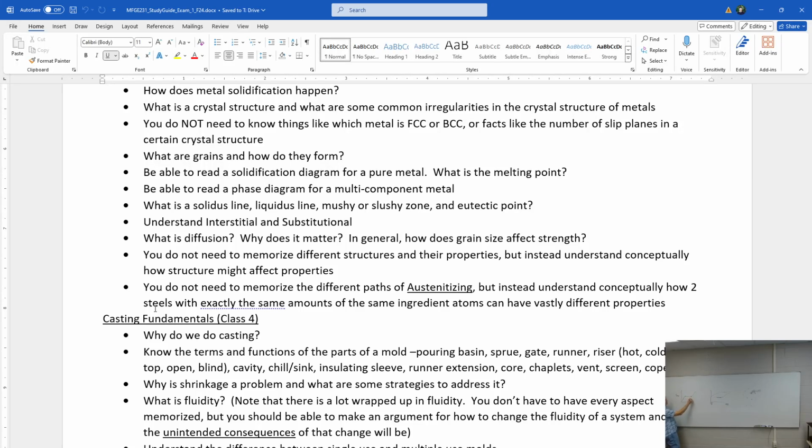Anyway, this section right here is the melting zone. So this section corresponds to this point on this graph over here. On this graph, because we're varying percentages, it is just this one corner where we see it is 100% of one of the components, and so it has a single melting point. When we move across here, we get these weird melting points that are kind of separated by the slushy zone. Over at the other end, where 100% is, we have the other melting point for the other material.